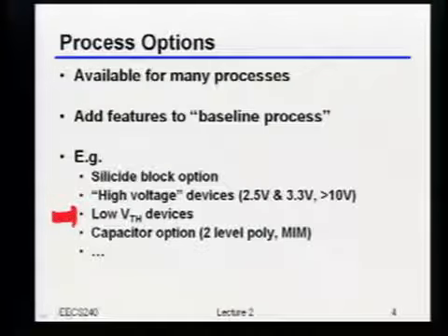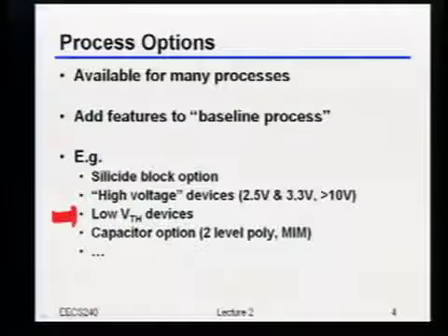Okay? And oftentimes you just basically run out of headroom to actually fit things inside of that supply voltage. So in some circuits, actually just the threshold voltage that you use on the device is kind of totally wasted, right? Because in analog, I'm trying to burn current through that thing the entire time, right? So I'm always trying to put some static bias on there. So sometimes you will actually get an option to have these so-called low VTH devices.